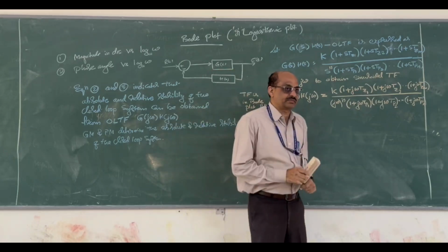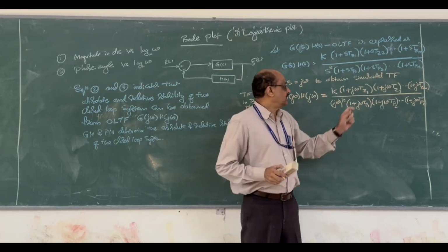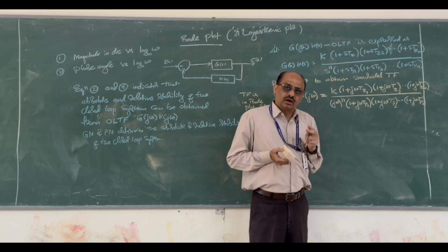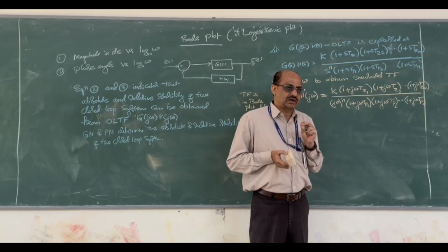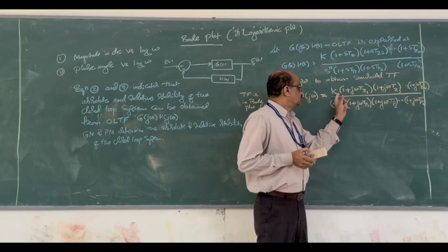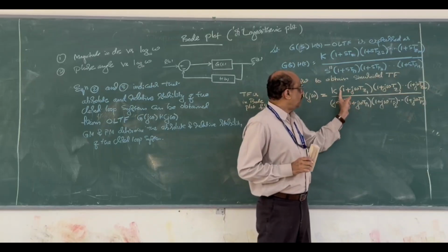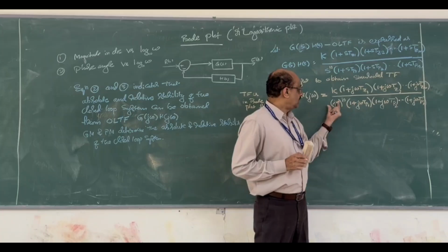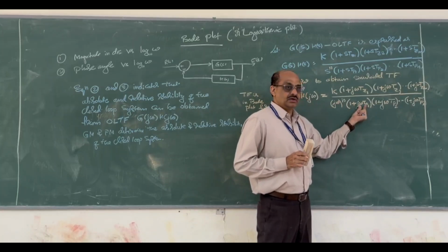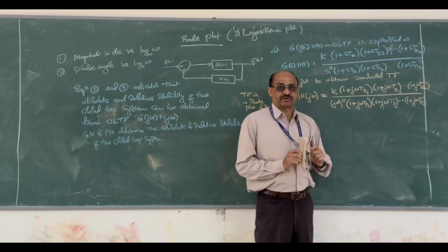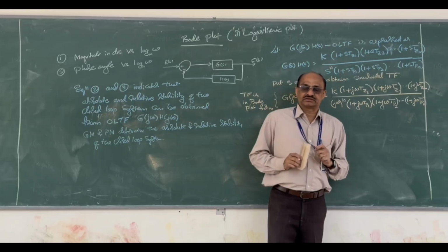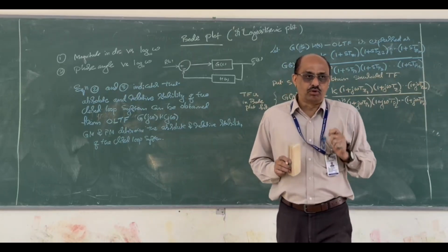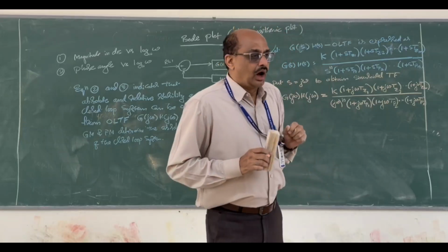You have to express all the simple zeros and poles, and one more, we get quadratic. I will explain that. So it should be 1 plus j omega T, not just 1 plus of j. You must express the given transfer function only in this form. It's termed as Bode plot form.